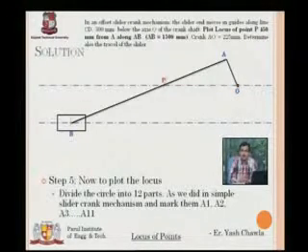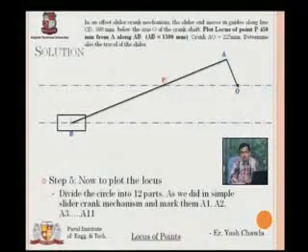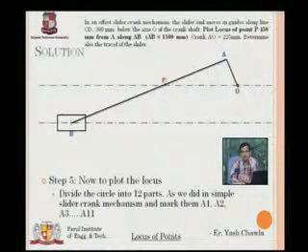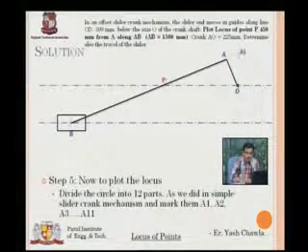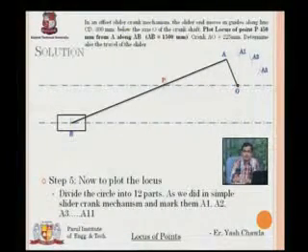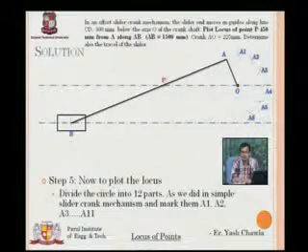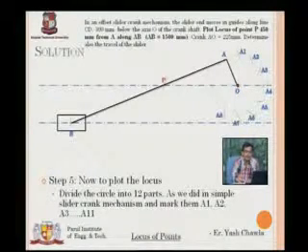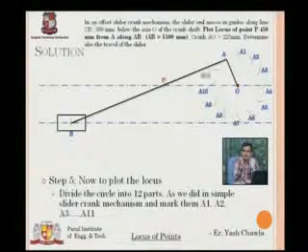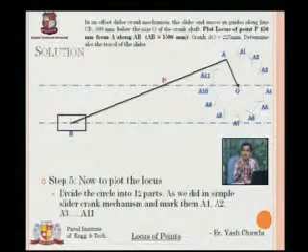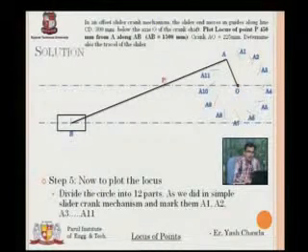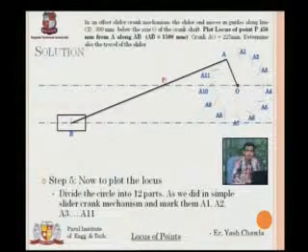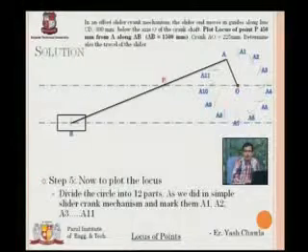So again what I'll do, I'll take my protractor, keep the center at O, the base AO, and mark A1. Here I have not shown the steps because we did it already. Then I'll take the distance A1, keep my point at A1 and cut an arc at A2, and that will go on and on till A11. So these are different points of my crank at different times.